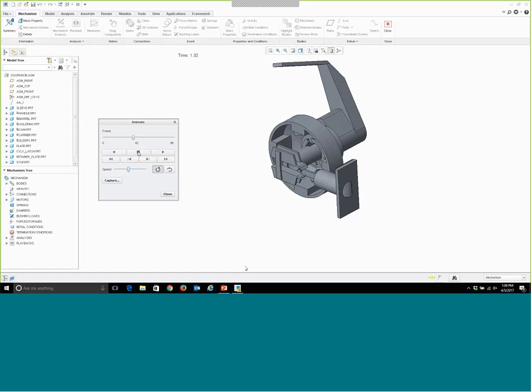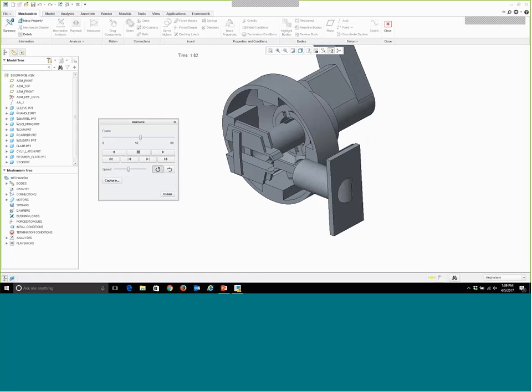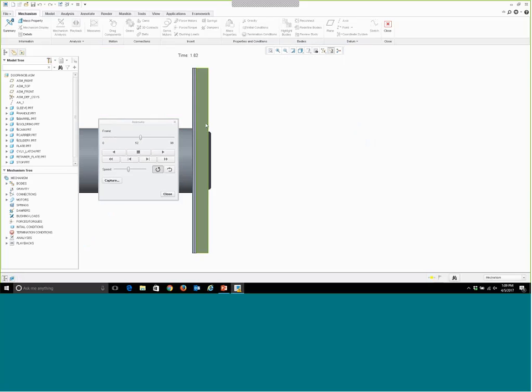And as I said, one of the key pieces to this is when the handle is in its open position, the edge of this has to be flush with the plate just to make sure that this doesn't catch on anything. And as we can see here, currently that's not the case, right? It doesn't completely go inside of the plate, so we have a bit of an issue.